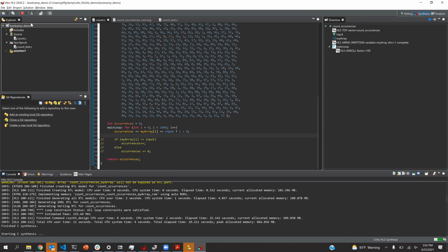What, 150 BRAMs? Yeah. So that means you can get 150 words out of memory every cycle if you wanted to. No, 300, right? They're dual ported. So you can get a lot of data out if you make use of all these BRAMs. And plus you have all these registers. If you start using them like memories, you can get stuff out even more.